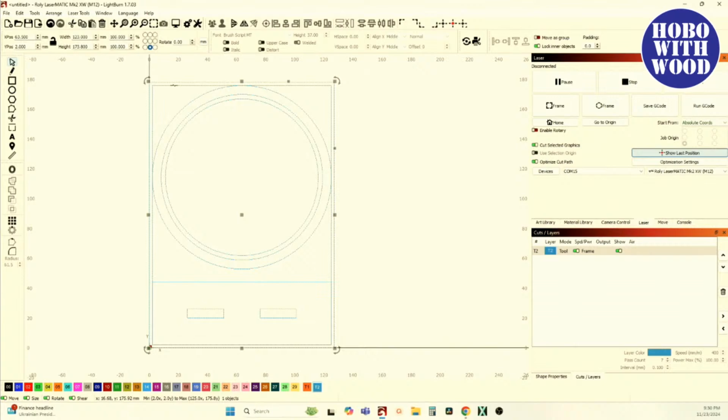This rectangle is 173.8. That seems kind of funky that it's an oddball number like that, but we'll leave it right there. We'll say 173.8. I'm going to change my anchor point back to the top, and I want to change my height to 173.8 minus 42. Okay. Now that rectangle takes up that amount of space. This is the base, and I've used every bit of that work area except for the 2 millimeters around the outer perimeter. Now I want to create the radius of this circle.